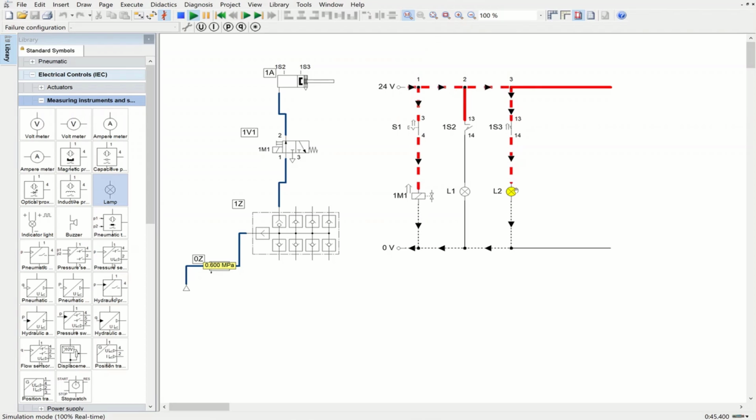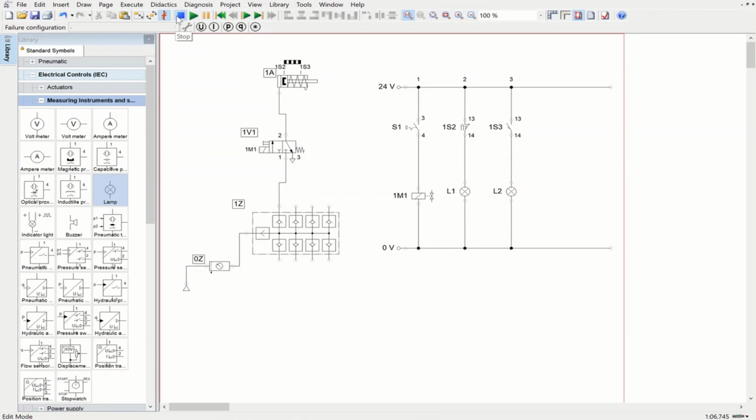So the big difference here with the previous circuit that we designed is the use of make switches and linking them to the position of the single acting cylinder, as you see here. Okay, so this is the second circuit. For the third one, we should adjust the pneumatic side too. So let me stop the simulation.